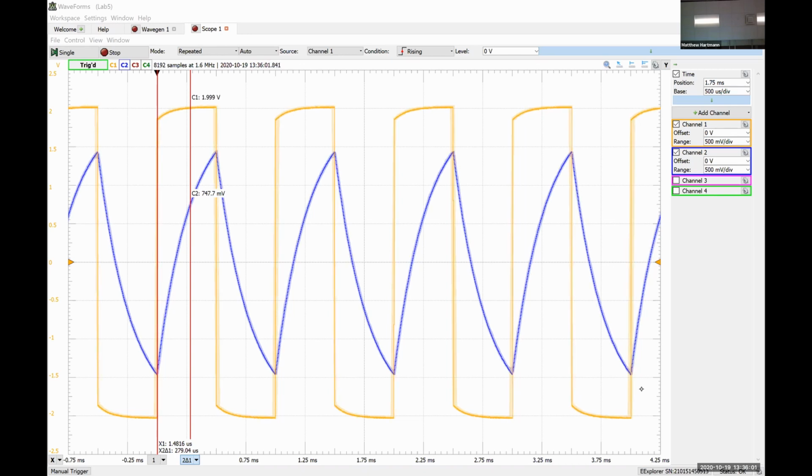We can see that it has a peak value of +2 and a minimum value of -2. There is a little bit of distortion in as much as there's some curvature, but it's as close to a square wave as we're going to get out of this board. But we can see the blue curve there, that is our capacitor voltage, okay? So it's never reaching the maximum value of the input voltage nor the minimum value, and it's because we're not giving it enough time to fully charge or discharge.